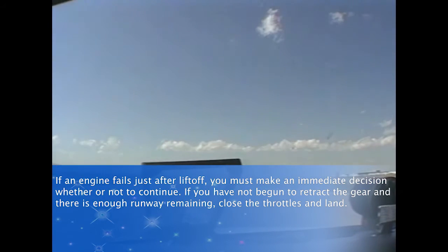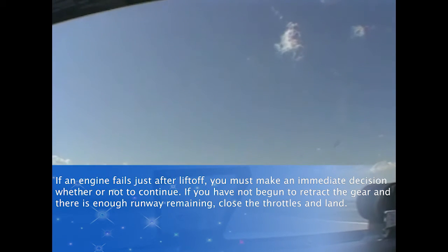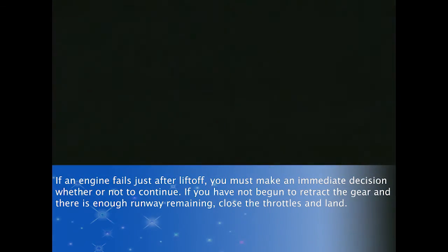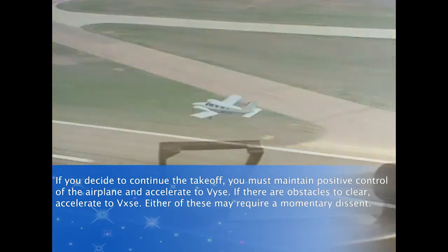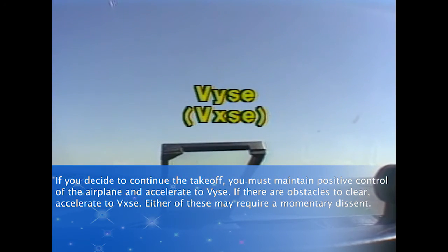If an engine fails just after liftoff, you must make an immediate decision whether or not to continue. If you have not begun to retract the gear and there is enough runway remaining, close the throttles and land. If you decide to continue the takeoff, you must maintain positive control of the airplane and accelerate to VYSE. If there are obstacles to clear, accelerate to VXSE. Either of these may require a momentary descent.